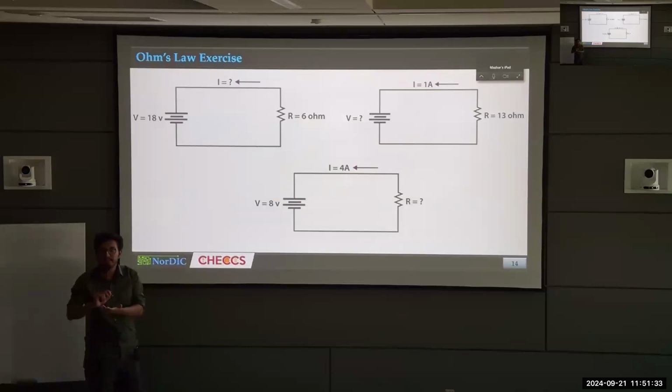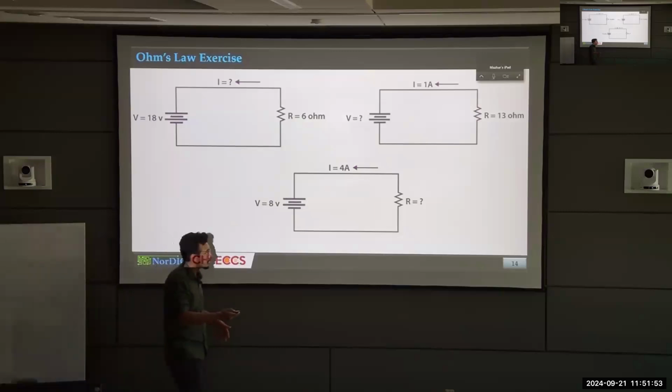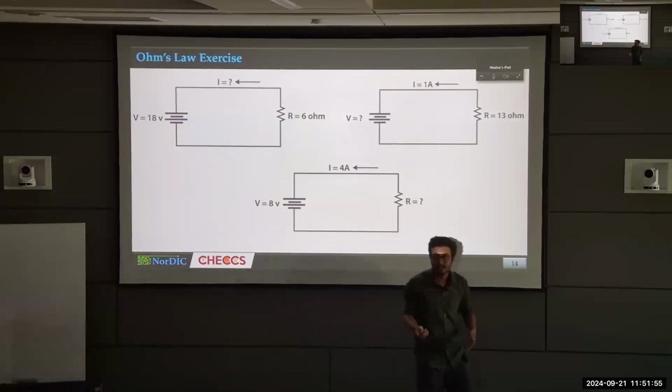No, you will actually give me an answer of minus 3 amps of current. Because I have specified what I want. I want the current from that direction to that direction. So you will give me the current is minus 3 amp to tell me that the current direction I have given is actually the opposite of what the current is actually doing. That's what Fatih has explained.